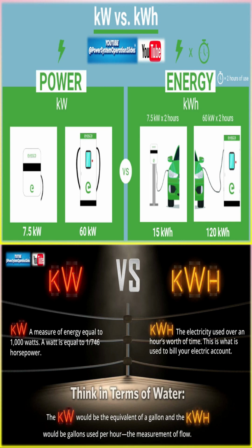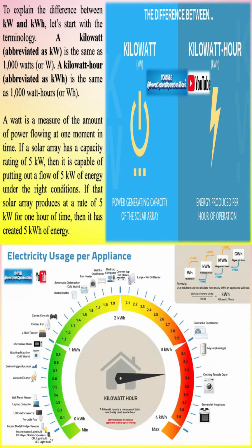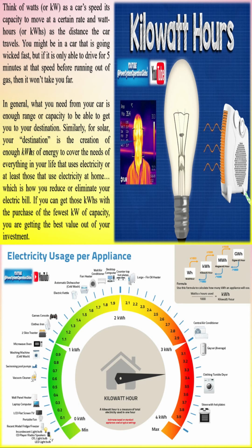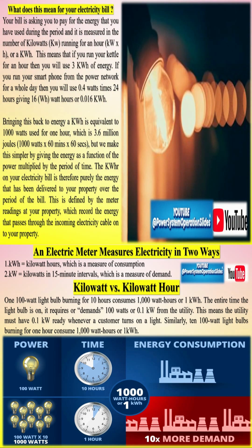Kilowatt-hour, unit of energy. Kilowatt-hour represents energy, which accumulates over time. In industrial or commercial settings, energy efficiency is key to managing operational costs. The goal is often to minimize kilowatt-hour consumption while maintaining productivity. Energy audits. Businesses often conduct energy audits to evaluate their total kilowatt-hour usage and identify areas for improvement. The audit typically examines each device's kW rating and how long it operates to calculate its total kilowatt-hour contribution to the facility's energy bill.